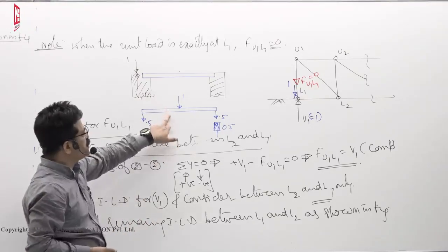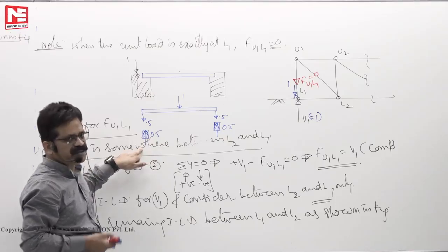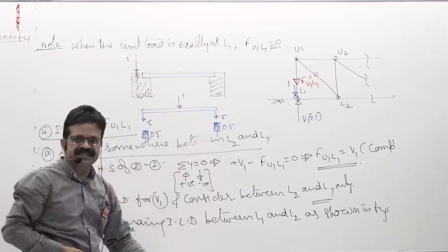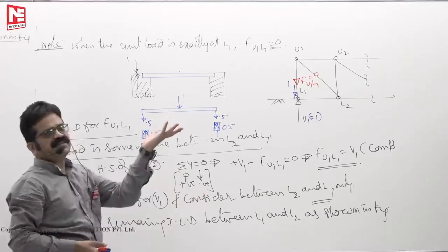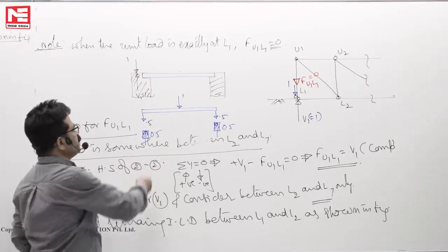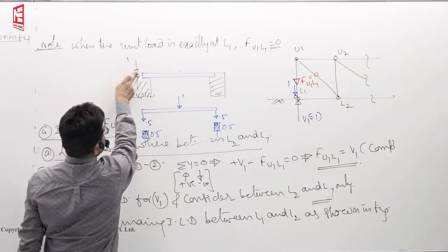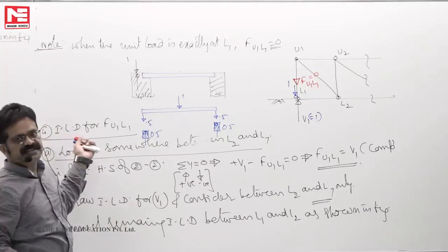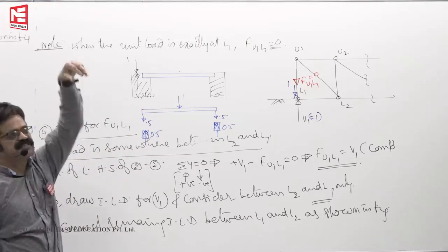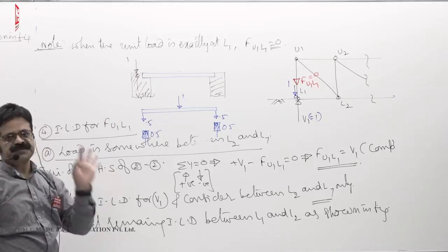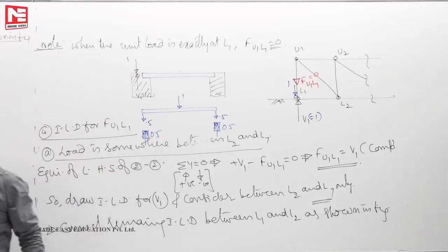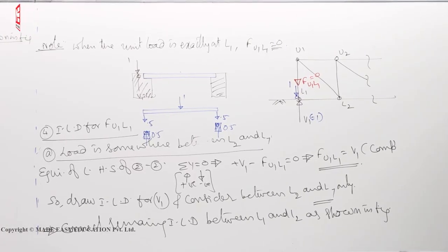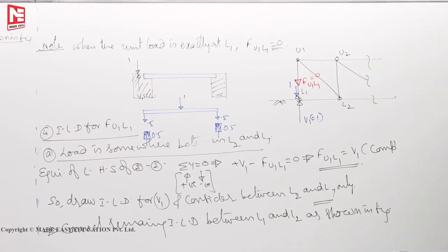Whatever force with which this beam presses this column or support, with the same amount it will exert a reaction. First the beam has to press it. If it doesn't press it, the support will not do anything. But without the beam, if direct load enters the bridge here, then it is a direct transfer, and this fellow simply keeps quiet. A similar arrangement is there in the trusses. Instead of the beam, there is a cross girder directly resting, so the load will be transferred to the support directly. So that's why that type of triangle comes. Okay. So I think now, from strength of materials, you know how the load transfer mechanism works.